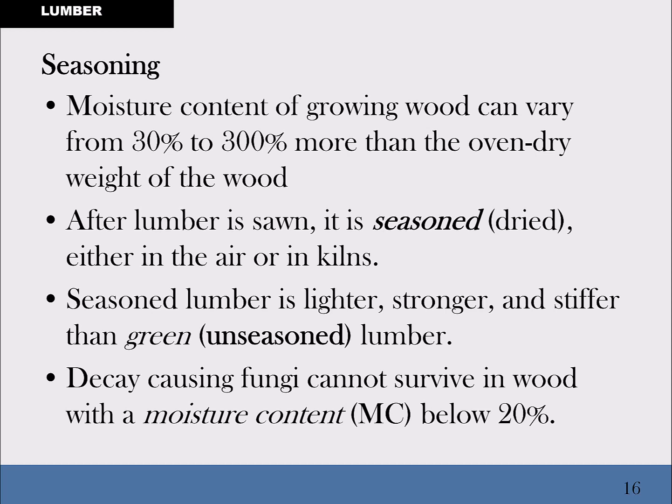So seasoned lumber is lighter, like I said. It's stronger and stiffer than green lumber, which is what we typically call unseasoned lumber. But unseasoned is also correct. More times in the industry, you're going to find people calling it green. Well, when you first cut it down, it's green, sort of, maybe. It depends. But we call it green nonetheless when it's heavy and full of moisture.